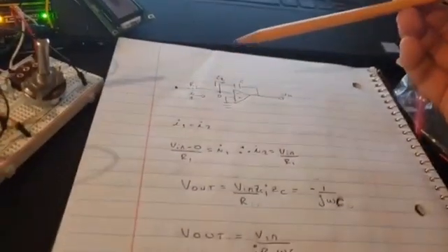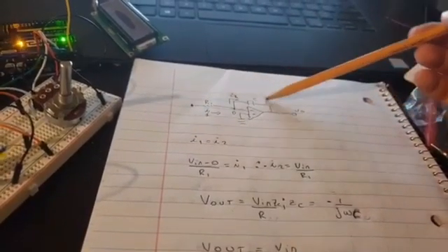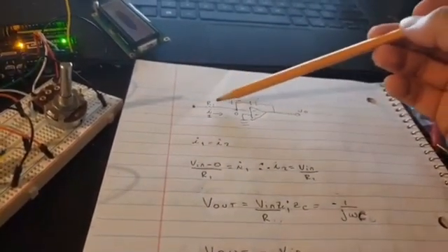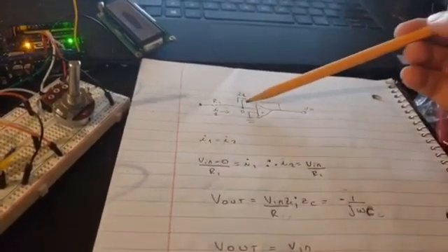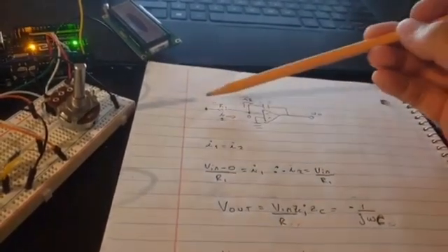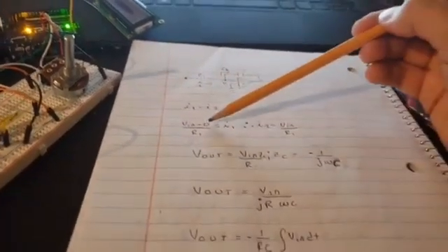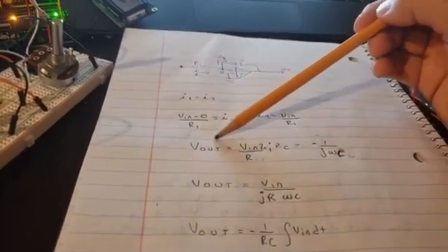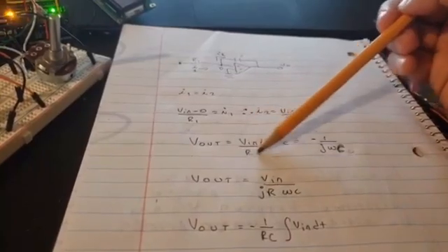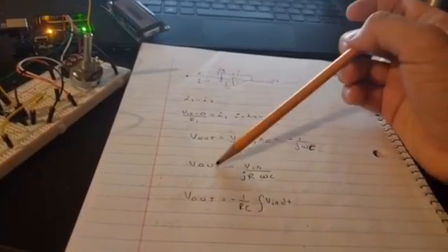Now moving to exercise number 5, we are given this amplifier where we have an R1 here, where we have a capacitor instead of a resistor. We know that there is no current flowing here, then the current here is going to be equal to the current flowing through the capacitor, and the voltage at this point is going to be 0. So we can calculate the current, which is just going to be Vin minus 0 divided by R1, and therefore this current is going to be equal to the current flowing through the capacitor, and we can calculate Vout, which is going to be equal to just the current times the impedance of the capacitor. So we end up having Vout is equal to this.